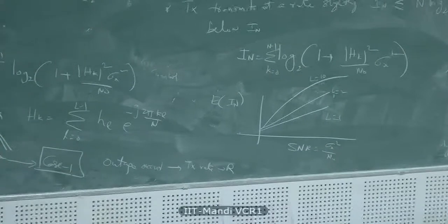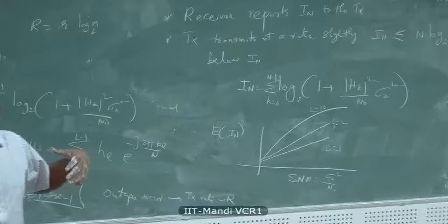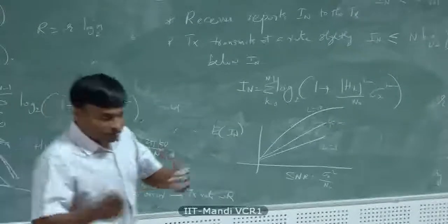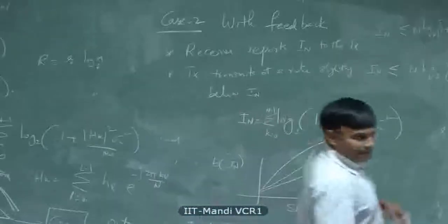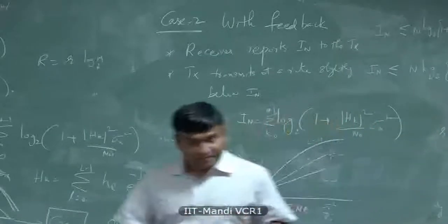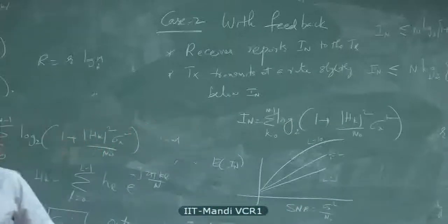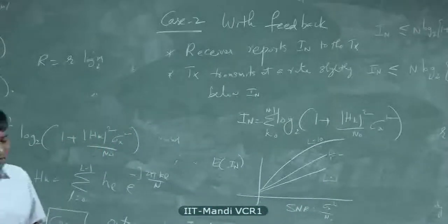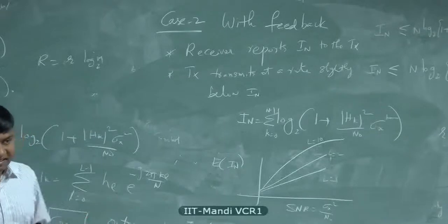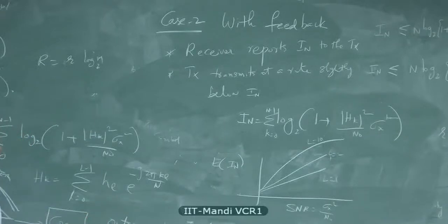And with that, at different points in the cell site, your SNR varies, and when you're closer to the base station, you pump a lot of bits through. When you're farther from the base station, fewer bits go through, or if your interference is high, you reduce. So you kind of adapt to the SNR. But of course, this feedback requires very quick feedback through an uplink channel, because wireless things are very unpredictable. The channel can change pretty rapidly.